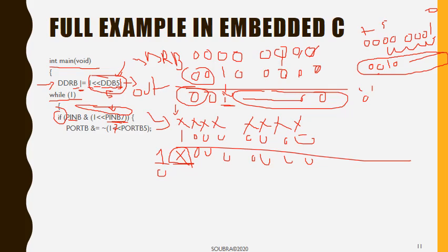So what I'm doing here now, okay, doing the same thing here. The port B5, remember I set it up as an output. So here I'm shifting the 1 to port B5, so the value of the pin B5 will be 1. Exactly as I did here for the DDR, I'm doing for the port register now. However, what I'm doing is negating. So this is the NOT to whatever result I'm having here.